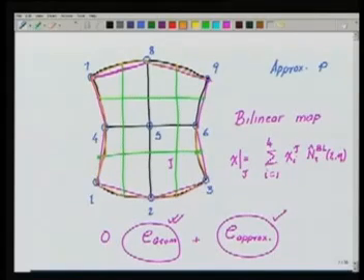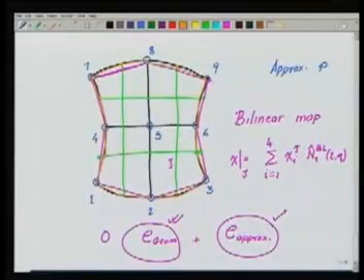So you see that the error in the representation of the geometry also has gone down, as well as the approximation error, because as we had said, when the approximation is of order p, we refine the mesh, the error goes as h to the power of p. The energy norm of the error, or the square root of the strain energy of the error, goes as h to the power of p.